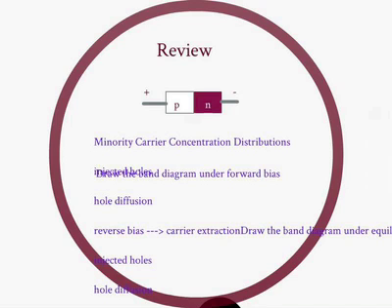So when you forward bias it, the Fermi level starts doing that, shifting by a distance equal to the forward bias, which means that the bands bend less. And what that means is that the energy barrier for the carriers is decreased.